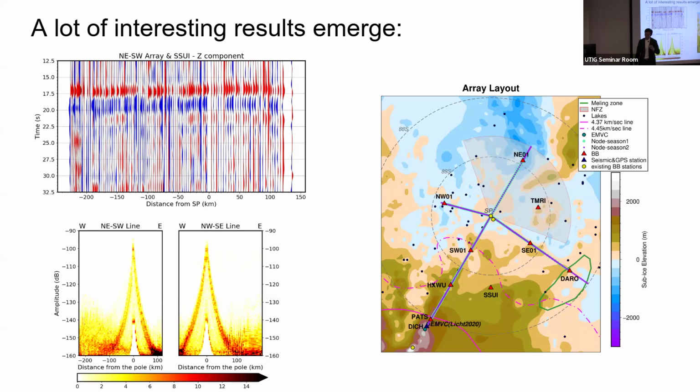And how do I do this? I'm not just saying I'm an ambitious person. I think the technology is there to allow a station to stay there a little bit longer. We just need to use rechargeable batteries and a new design of the power system. We need to capitalize on the wind there, especially on the high plateau. We need to send the data back without servicing it. Currently, we have to service it every year, and that's expensive. If we can solve that problem, a station can be deployed there for 3 to 5 years, and you don't have to touch it.